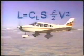Referring back to the lift formula, you can see that there are only two variables that are pilot controllable. First, by varying the angle of attack, you govern the coefficient of lift. In addition, you can normally regulate the velocity of the relative wind by changing your power setting or flight path.